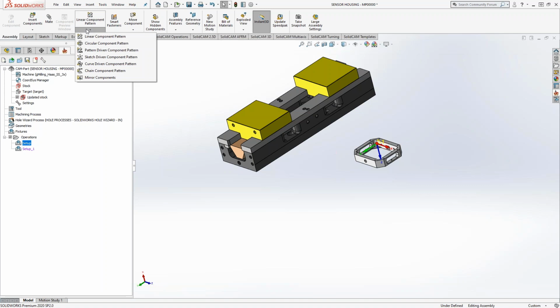And the idea of mirroring it works for when it's just the side 1, side 2. But that's not going to work when you have to flip the part 90 degrees or give it a different setup completely. There's different solids. So this overall is a procedure when you bring in your vise, your clamps, your work holding, and you mate them however they need to be mated. But one option, one quick, simple option is to mirror it, because it literally is just a side 1, side 2. So you could mirror it, but then there are some limitations with that.